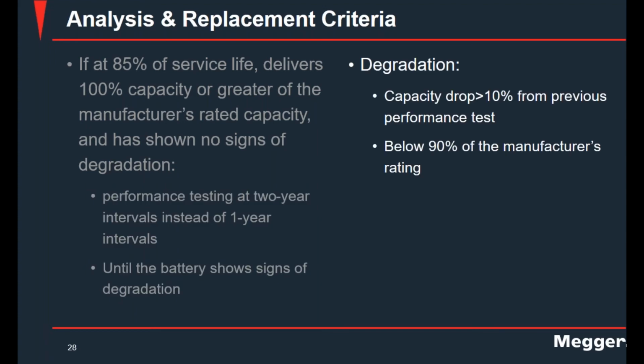Then when to replace the battery? When the capacity reaches 80%, that's when we need to replace the battery. From this point on, the curve of the change, or the capacity degradation, will be faster. There's a knee point, and the capacity will drop very fast from that point. Once we get to 80% in a battery, we have about a year to replace it. That's the time you need to go through the specification and purchasing process.